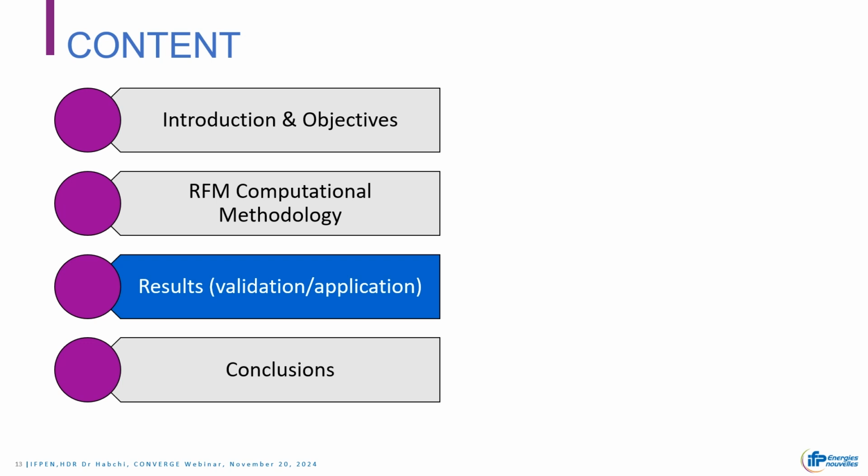And if you are in two-phase, it tells you also what's the volume fraction of liquid and also the composition of the liquid and the gas. So this is a powerful method that allows the computation of dissolved gas inside the liquid as well.